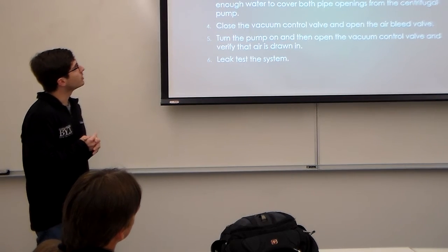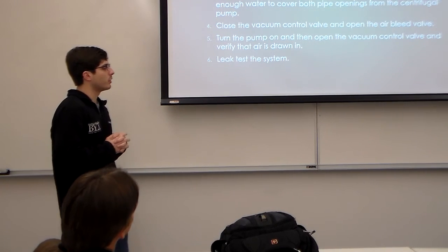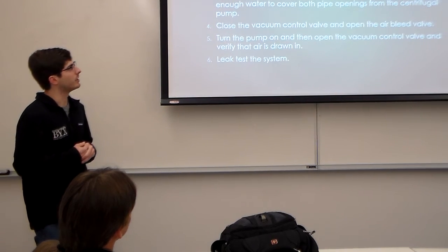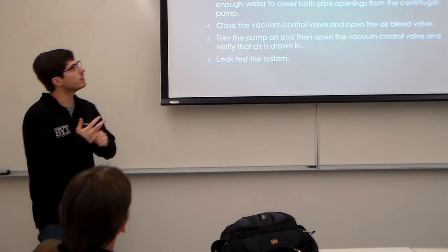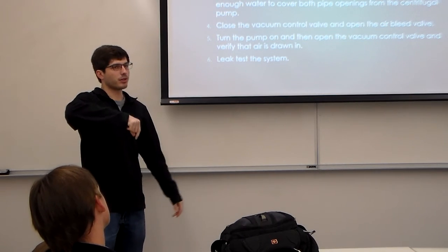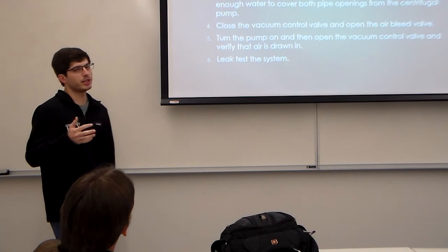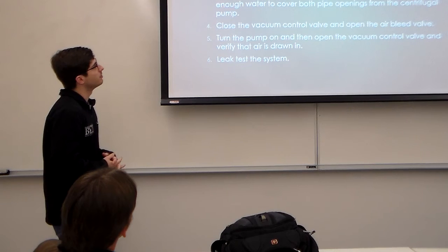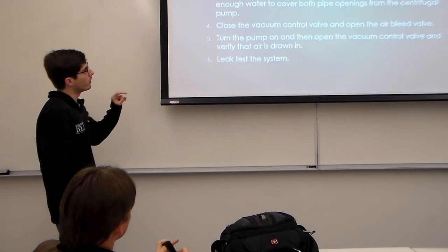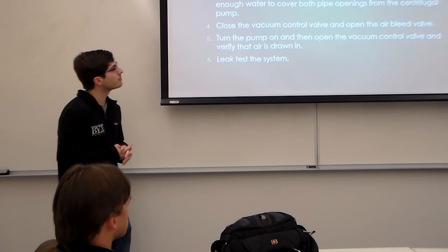Next slide. For the setup, our instructor will specify the use of boiling beads. This is because we want to make sure the heat is evenly dispersed and that we can create bubbles in the boiling so that you don't have any accidents or discrepancies in the data. Another thing to highlight is that where we place the thermocouple tip is very important. As we learned last week, if you touch the edges of the flask or the beads, they can mess with your data, so you want to keep it just in the water with no interference. And lastly, we want to leak test the system to make sure there are no leaks that will cause any discrepancies.